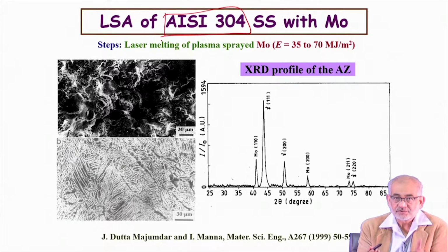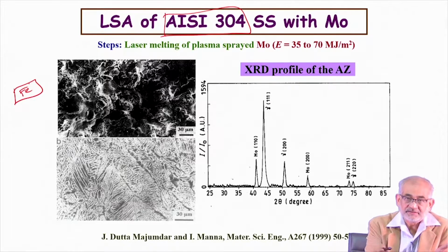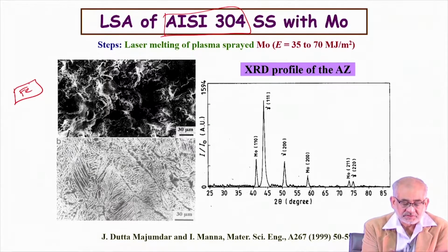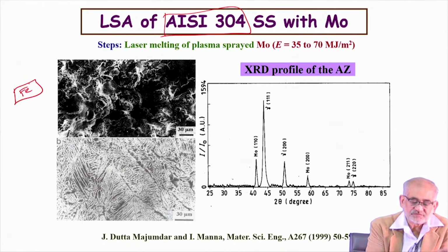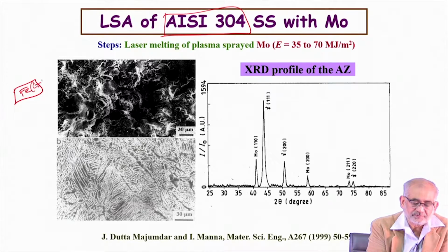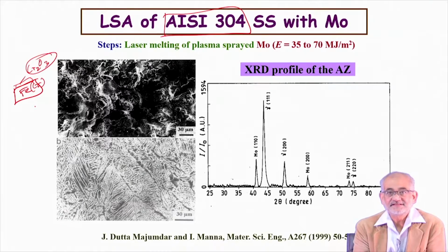So in order to prevent oxidation, what you do is very interesting. If this is iron and you expose it to any corrosive atmosphere, it will immediately form iron oxide and iron hydroxide or certain carbonates and so on, and they fall off and then expose a fresh layer and oxidation continues, and that's how it gets corroded. We see rusting. In order to prevent rusting, if you alloy this with chromium, this chromium sits on the surface and throughout, but the chromium atoms at the surface will immediately form a protective layer, which is typically a chromium oxide layer, a fairly adherent layer. So it prevents any further oxidation, any further corrosion, and doesn't allow rusting to proceed at all. So we get a rustless or stainless steel.